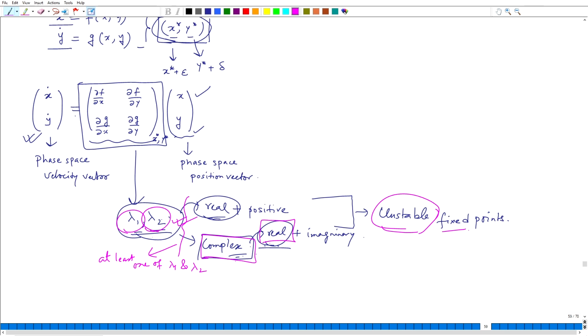Then there is also a specific case where the real part is 0 for the complex roots and the imaginary part is the only surviving part. In that case, although there is no decrease of perturbation, there is also no increase in perturbation, because an imaginary part means it will simply maintain the same magnitude.